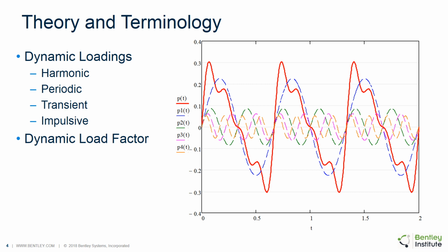Let's take a closer look at the red curve, which, as I said, is the design footfall curve that we're going to use in our implementation in this presentation. This curve was actually constructed from a series of measured footfalls. They measured a large number of footfalls, studied the patterns, and then created this design curve, which was meant to represent a curve with a minimal probability of exceedance.